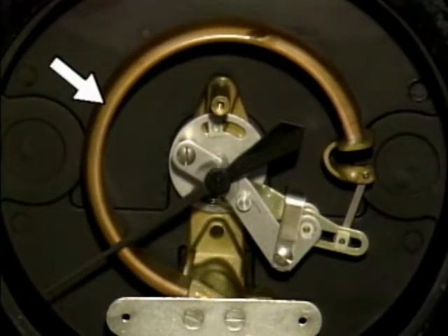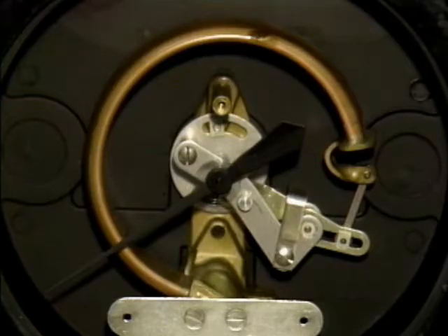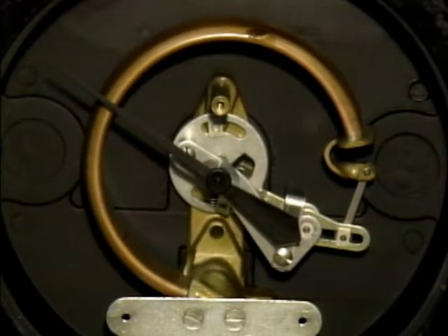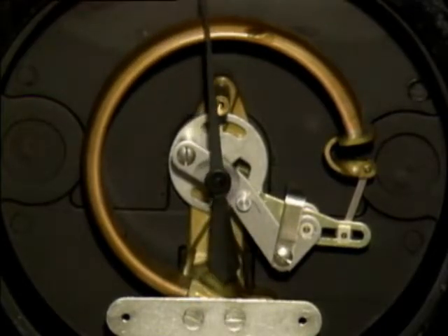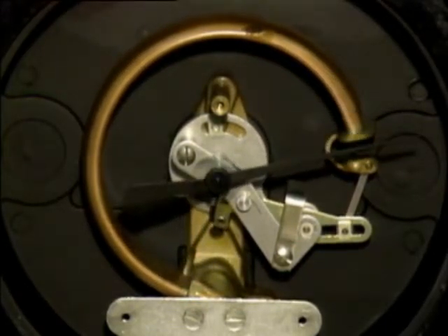This is a C-type Bourdon tube, named for its shape. One end of the Bourdon tube is attached to the pressure source, while the other end of the tube is closed. When pressure is applied, the tube tries to straighten out. The closed end of the tube moves in proportion to the amount of pressure applied. A mechanical linkage converts the movement of the tube to pointer travel.